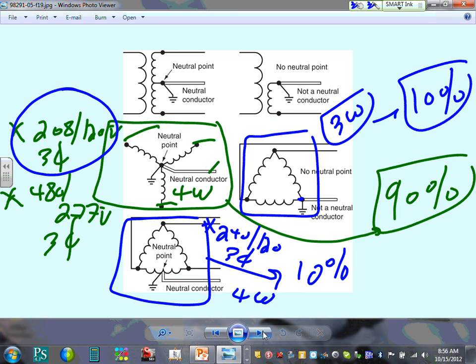A place where you have a lot of 3-phase loads and a very tiny single-phase load. Lift stations use a system like this. Well houses use a system like this, where the motors are running at 240 and the lights and the receptacles are running at 120. Can you give a thumbs up, Chad?